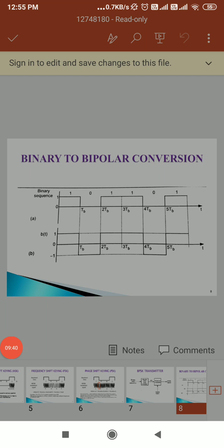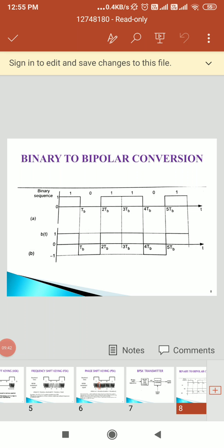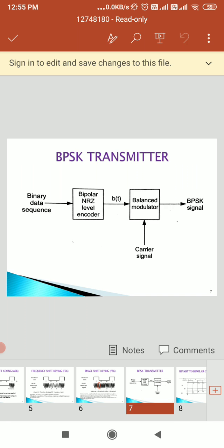So the modulation technique which employs coherent detection at the receiver, we call a coherent modulation technique. And if we talk about non-coherent, how can we describe it? In non-coherent detection, knowledge of the carrier wave is not required, or the receiver need not be phase locked with the transmitter, since we do not require the carrier to be recovered or correlated with the received signal.